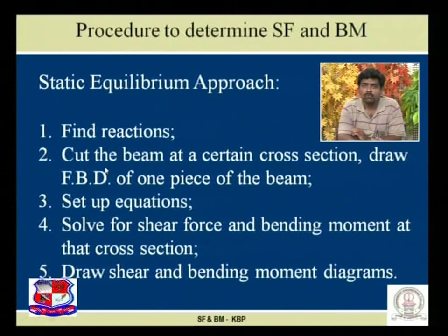Then we have to cut the beam at a certain cross section and draw the free body diagram of one piece of the beam, either left of the section or right of the section, and determine the shear force at that particular section using the basic concepts, meaning we have to set up the equations.